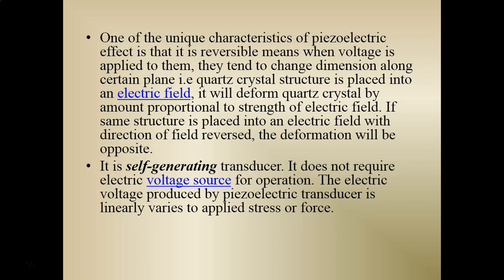So another unique characteristic of the piezoelectric effect is that it is reversible. That is, when voltage is applied to them, they tend to change dimensions along certain planes. Already we have seen under electric transducers that if you give any force or stress, it is converted to electrical form. So reversible means that, again, from the electrical form, it can be converted to the physical quantity, like stress or force. That is, the crystal dimension will change when we apply an electric field.